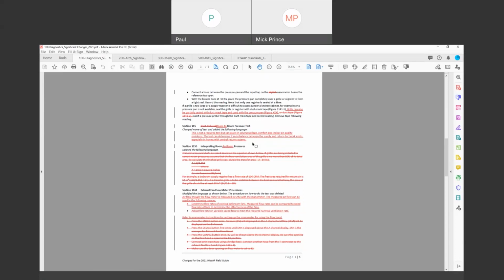And it's really important where you have central returns, that is, supply only in the rooms. So when someone closes that bedroom door, how does the air get from that room back to the return grill, usually out in the hallway someplace? I'm assuming that there could be performance issues in those homes where the return air can't get back. Right, performance issues and comfort issues. If a client complains that their bedroom is too hot during the summer or too cold during the winter, well, if air can't get out of the room, air has trouble getting into it. So it could be a comfort issue as well.